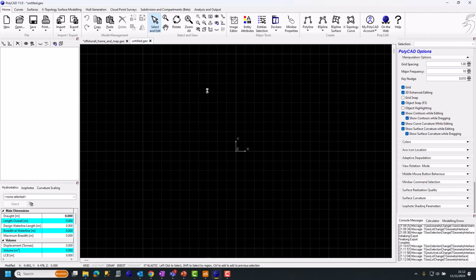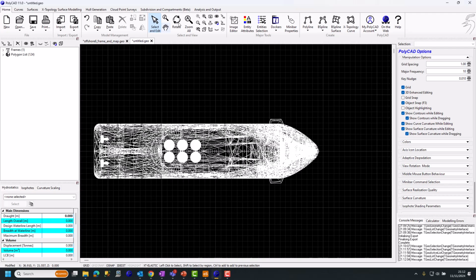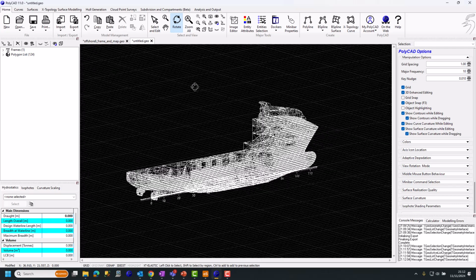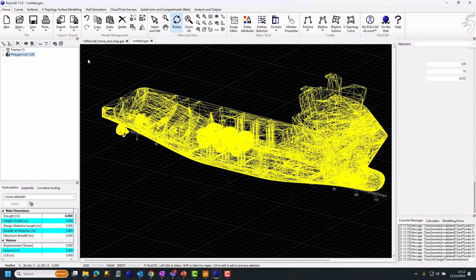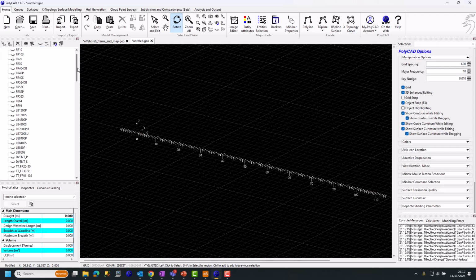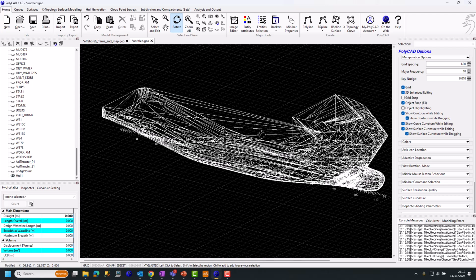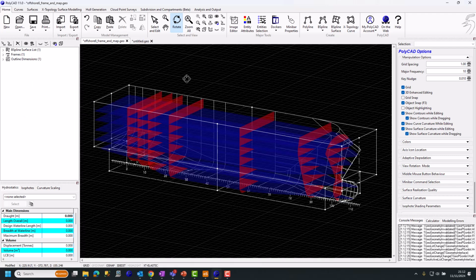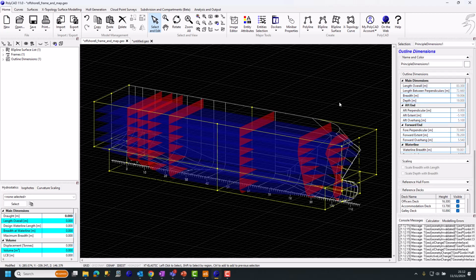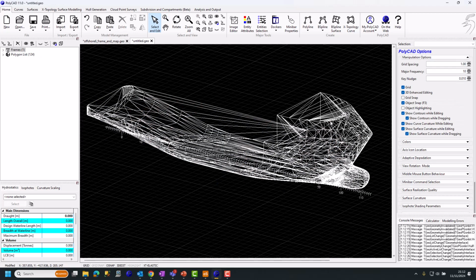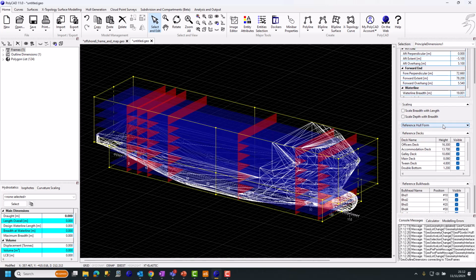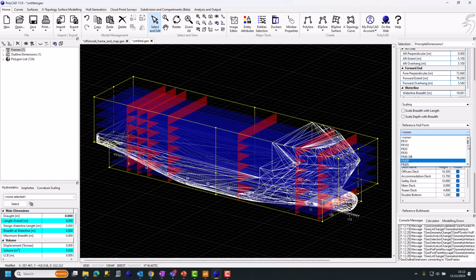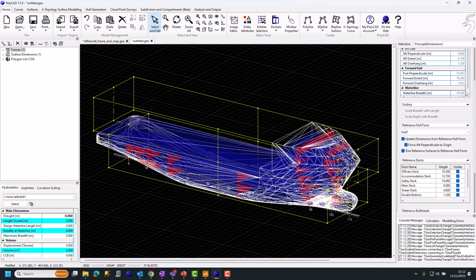In this final section, we're going to use an external model file. In fact, since we've been dealing with an Aveva Marine project, we're going to take an Aveva Calc geometry through into the coordination of this project. We'll start by turning off and just focusing in on the hull volume. And what we'll do is copy and paste the coordination information from the previous preparation and attach it to the new hull form. So now you'll see that when I select the new hull surface, everything recalculates, and I will need to adjust the draft because it didn't know about it.